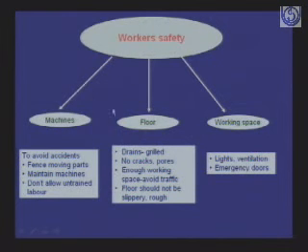For worker safety, you have to consider that your machines are laid out properly, there is fencing of the moving parts, machines are maintained properly, and you should allow only trained workers, trained manpower, to handle the machines.